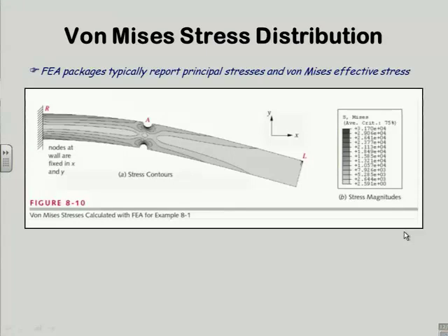Yeah. But on the other hand, from a design perspective, why have you got a triangular notch? Because you've got horrible stress concentration. I say, no, I don't want that. I'm going to put a round bottom on it to get the stress concentration down. So I never encounter that problem because I wouldn't allow it in my design. Okay. And you'd be improving the design if you changed it to something more gentle, like this notch I show here.